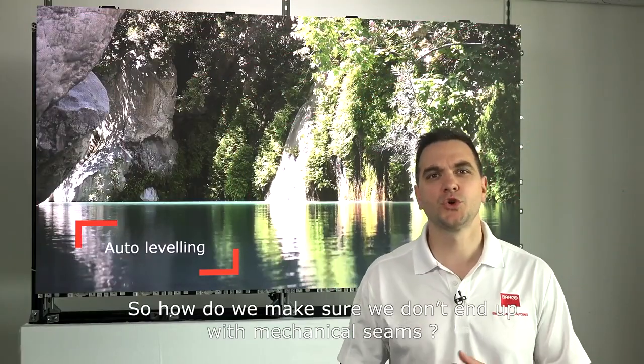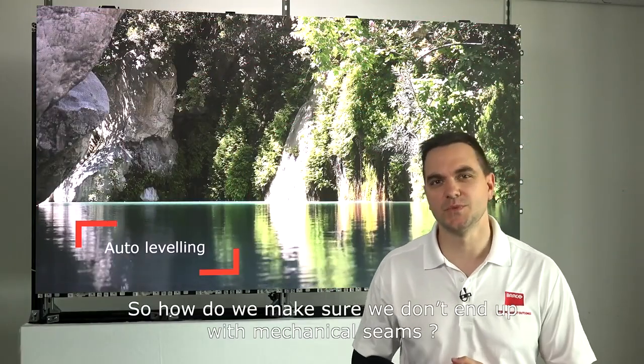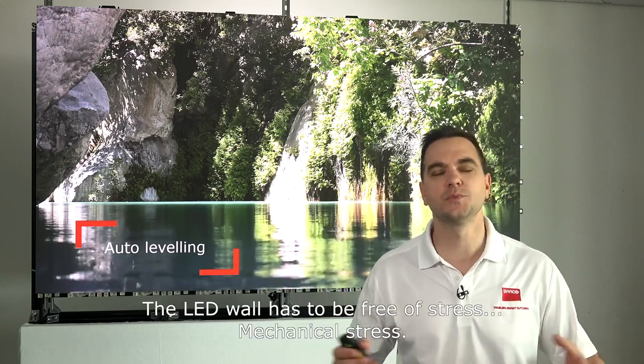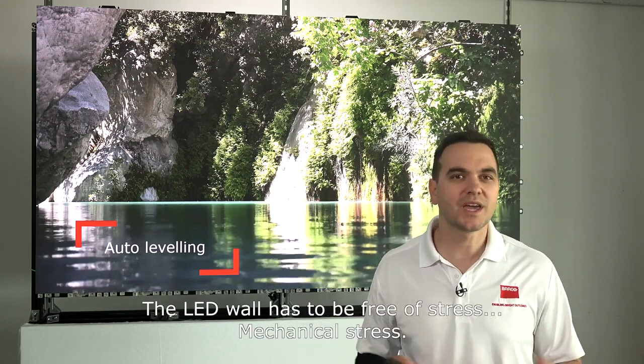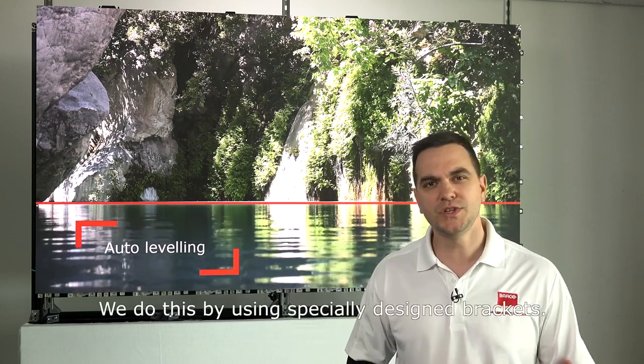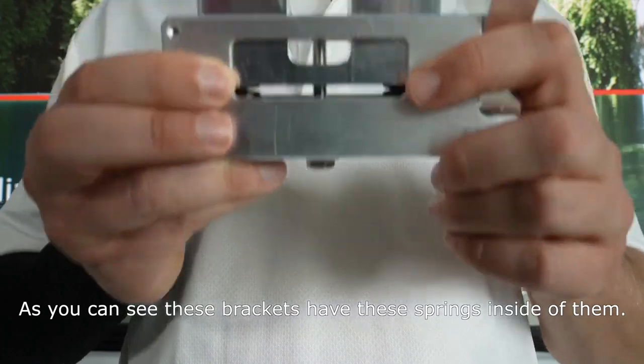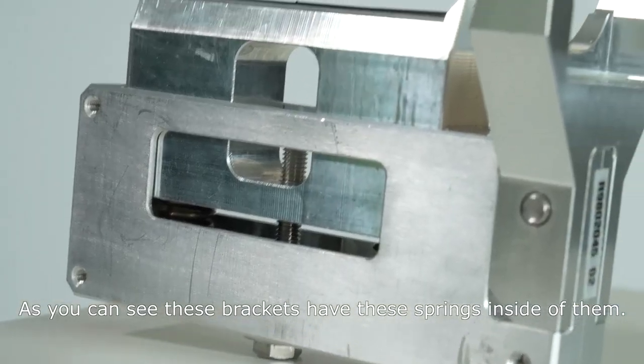So how do we make sure we don't end up with mechanical seams? We tackle this problem at the roots. The LED wall has to be free of mechanical stress. And we do this by using specially designed brackets. And as you can see, these brackets have springs inside of them.